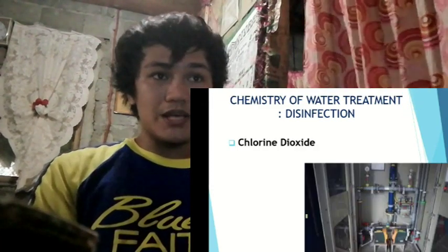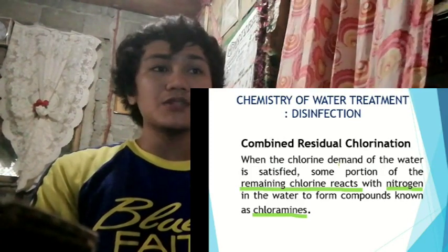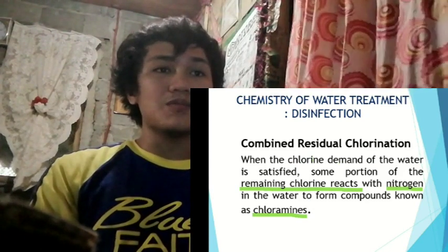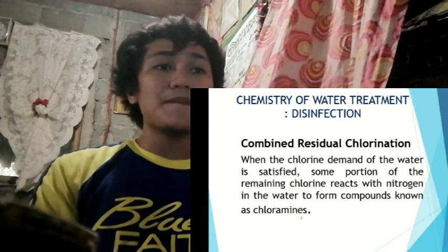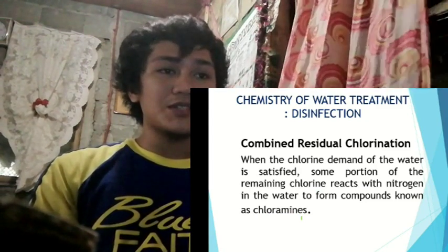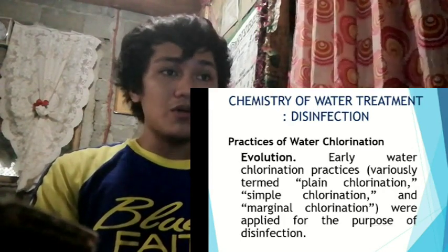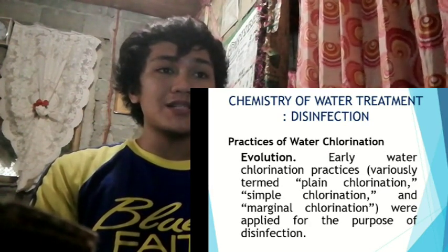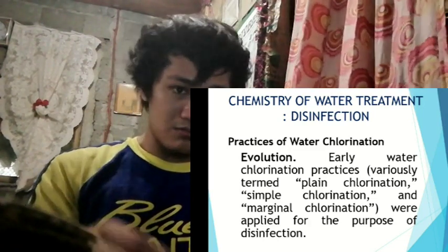Free residual chlorination. Free residual chlorination practice involves the application of chlorine to water to produce, either directly or through the destruction of ammonia, a free available chlorine residual and to maintain the residual through part or all of a water treatment plant or distribution system. Free available chlorine forms have higher oxidation potentials than combined available chlorine forms and therefore are more effective as oxidants.